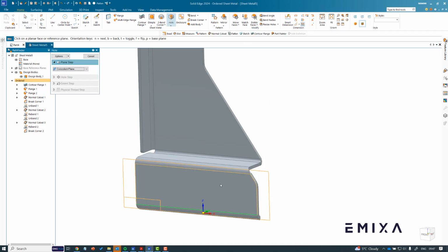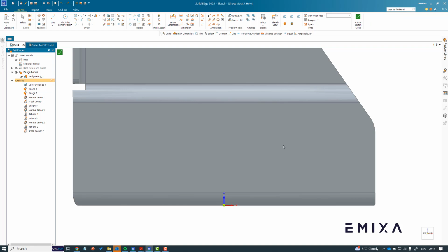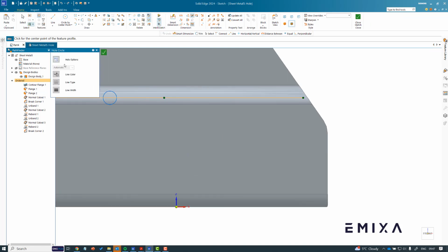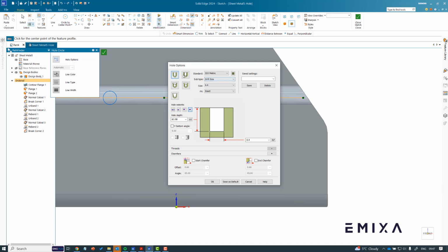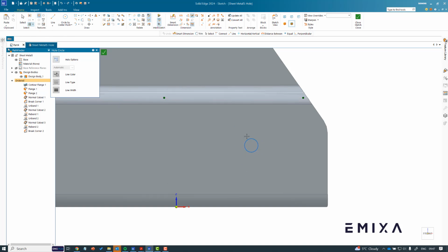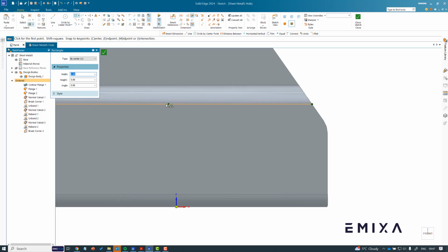We're going to follow the same kind of process that we did before. So we need some 6.4mm holes down here for mounting. So I'm going to go to my hole options, to this drill size option, and that's got my 6.4 in there, as I must have used that before. And I'm going to do my cutout on here the same as what we did before. So it's 25-25 because it's mounting to that block that we've done previously.